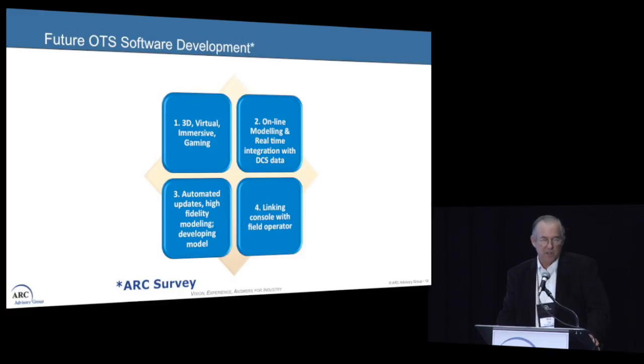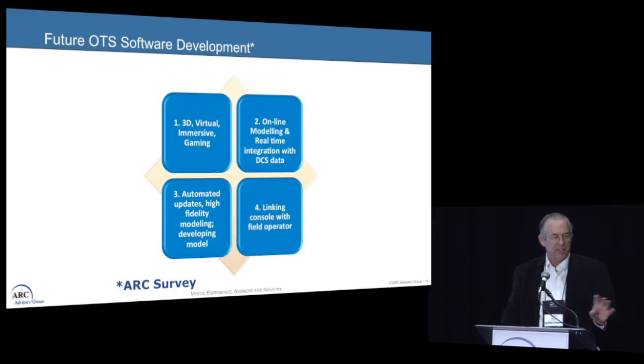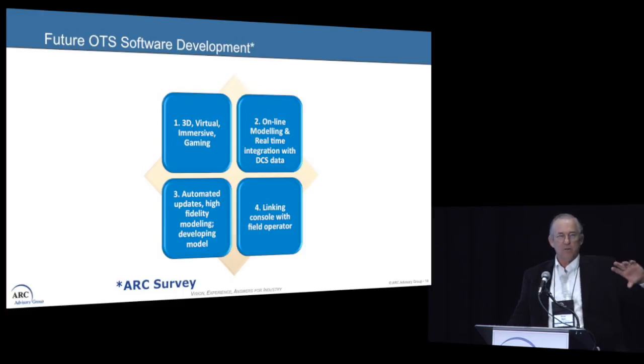With regards to online modeling, as I mentioned, you have to optimize fidelity. Some of the biggest complaints about why we didn't build the simulators is that it's too expensive to maintain. And one of the other things is that control strategies change. Oh, I adjusted the alarm setting. Oh, I adjusted the tuning parameters. Oh, I adjusted this extra override to protect it.